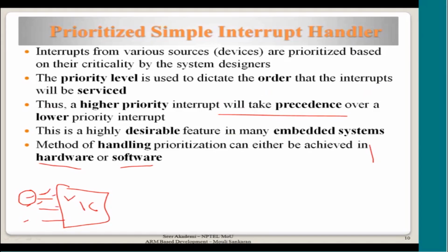Though both of them are generating the interrupt, it will first ask the ARM processor to process the high priority one, and once this is serviced, it may say okay, if this is also enabled, since individually you can enable an interrupt from a source or not. So it can decide the priority based on the hardware.